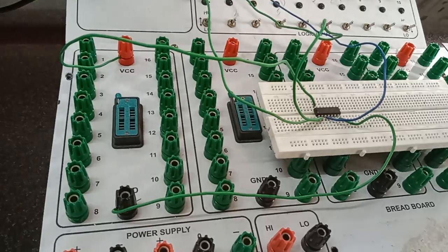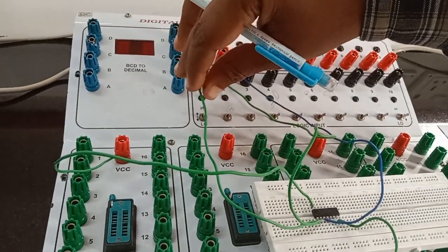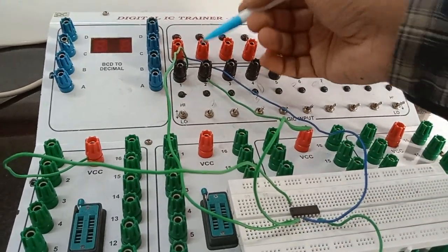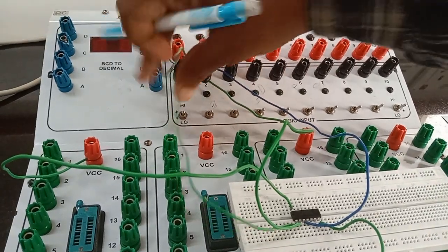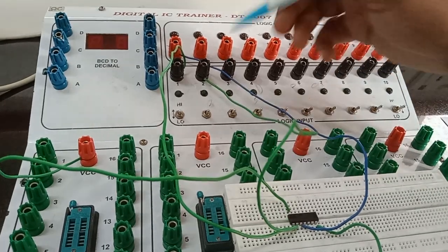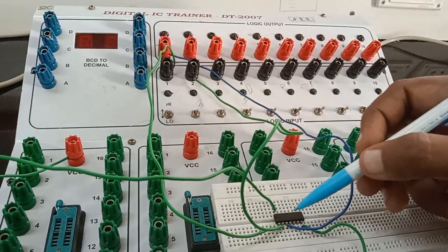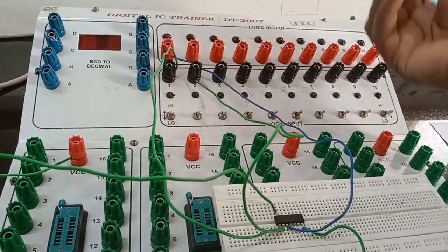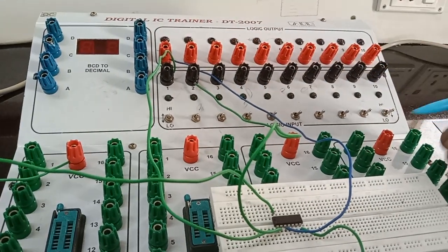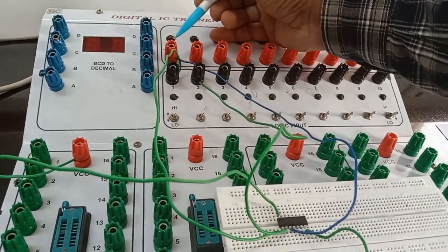It has two inputs. One is pin number 1. We are using wires. With the help of this wire I am going to give the input from the IC to the input port. This is input 1. This wire connects to pin number 2, that is input 2. So totally we have two inputs. Pin number 1 is one input and 2 is the other input. We consider this is A, this is B. The output is Y equal to A dot B, that is the multiplication is the output. Pin number 3 is the output, and I am going to connect it.